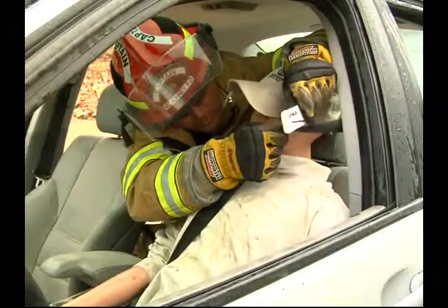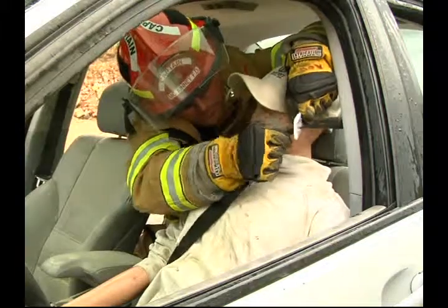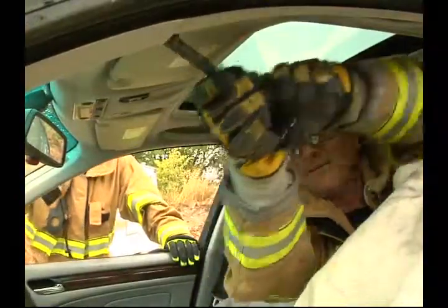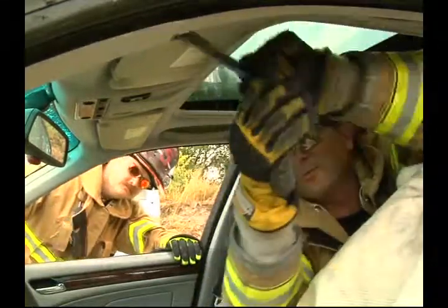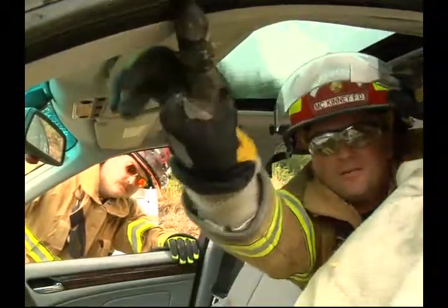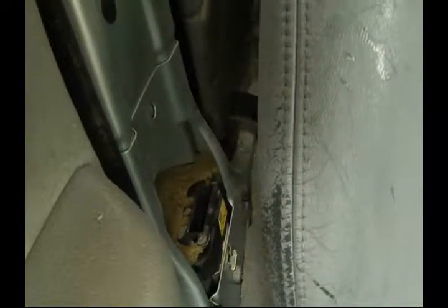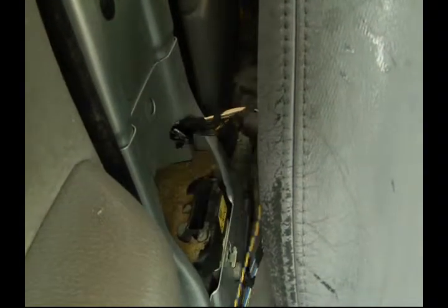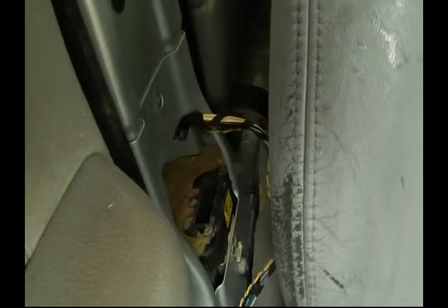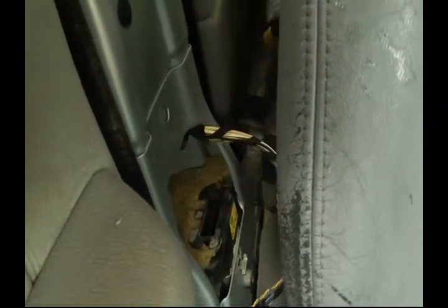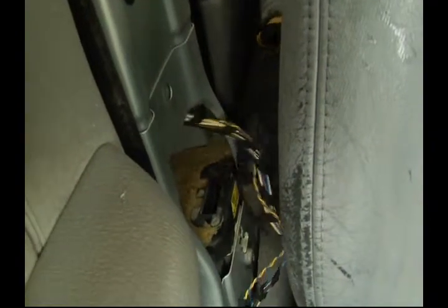To begin, cut all the seat belts and peel away the inside trim material along the pillars and roof line. Locate any undeployed airbags in roof-mounted side impact airbag systems. This will also reveal seatbelt pretensioners, which are usually mounted in or on the B pillar. When you have located all of these items, mark or make note of them to avoid cutting them during the evolution.